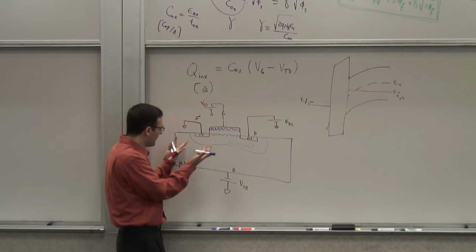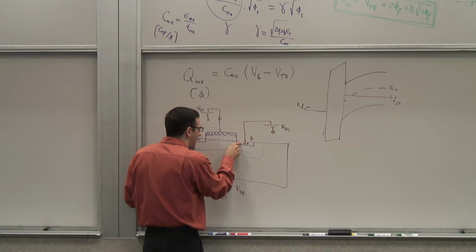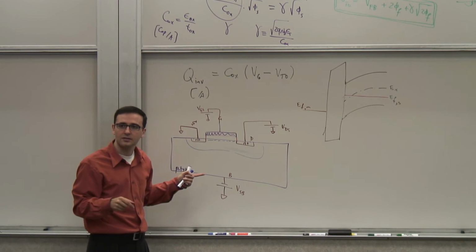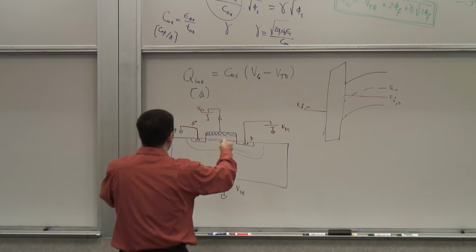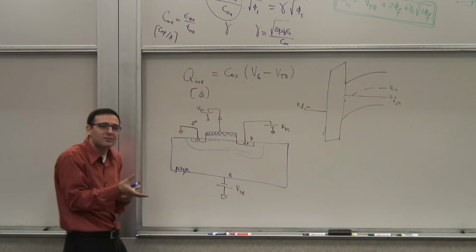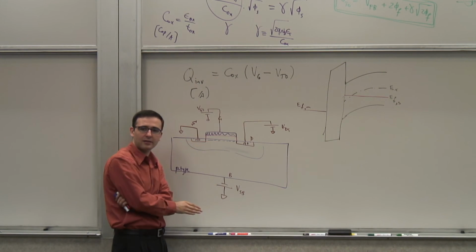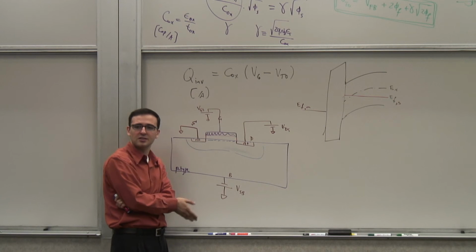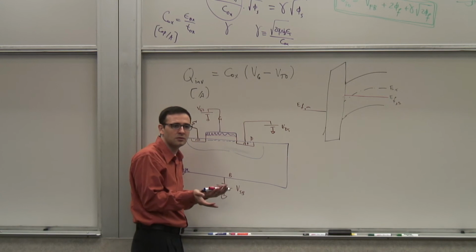Now, when you see that, even on this surface, in the simplified picture, you have basically a channel formed by N-type. So it's N plus, N, N plus. So you can carry current. Now, this current flow, due to the electric field, if you apply a small electric field here, there will be current flowing, right? This current flow is basically a drift current flow, right? Because at the surface, are these electrons majority or minority carriers? They're majority because you've changed the surface to N-type. You've inverted the surface. So they are majority. There's plenty of electrons available.